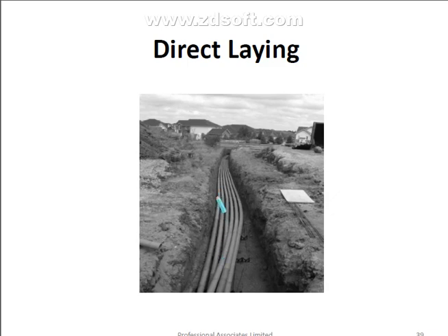You have to dig down in so many areas to see where the breakage is or where the fault is occurring. So maintenance cost is quite high, and it is not so convenient in a congested or crowded area where it is not easy to evacuate the system. So this type of direct laying can be done in an open area only.